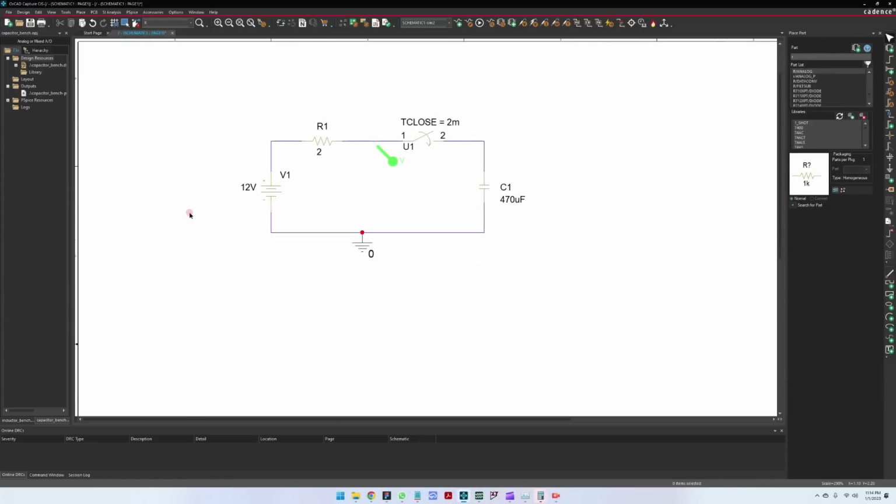Okay, so before moving forward with the simulation, we need to add one more thing to the schematic. We would need a load, because this is an ideal capacitor here, and being an ideal capacitor, it would just charge instantly and would not have any load to drive. So for this, I'm going to use a resistor. In this case, I'm going to leave it at a 1 kilo ohm resistor so that we can have some leakage current going through this resistor here.